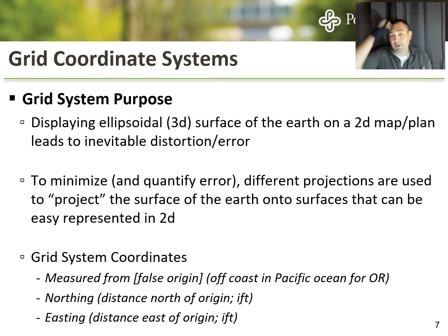But that inherently causes some distortion, and so we need to be able to quantify what that distortion is in order to then minimize it. And there's multiple ways that we can minimize it. Usually it simply means that instead of one cone to approximate all of the points in North America, we break it up into like 200 cones or 200 cylinders, for example. That's the way that we oftentimes would minimize that error.